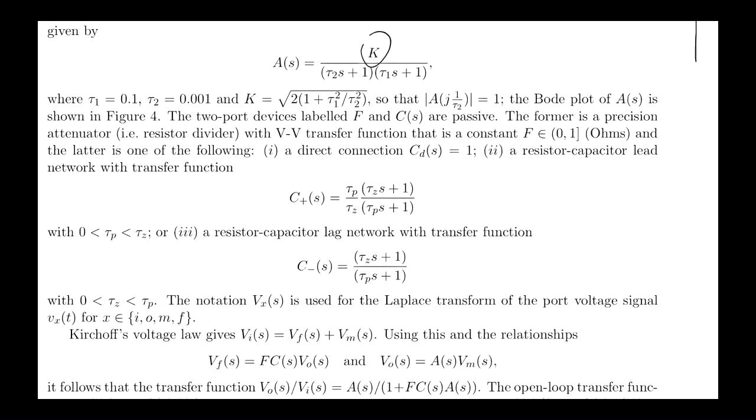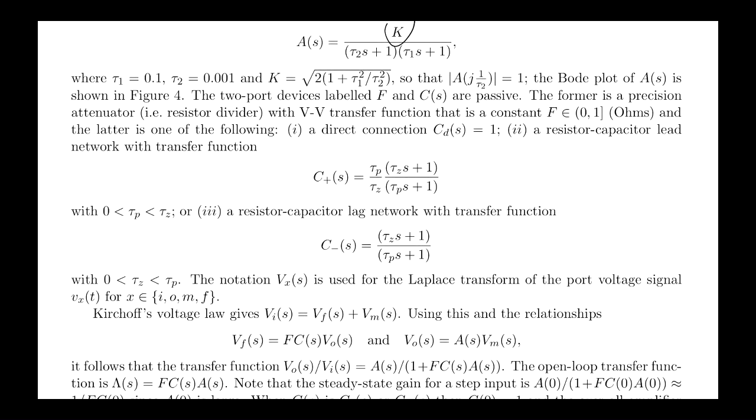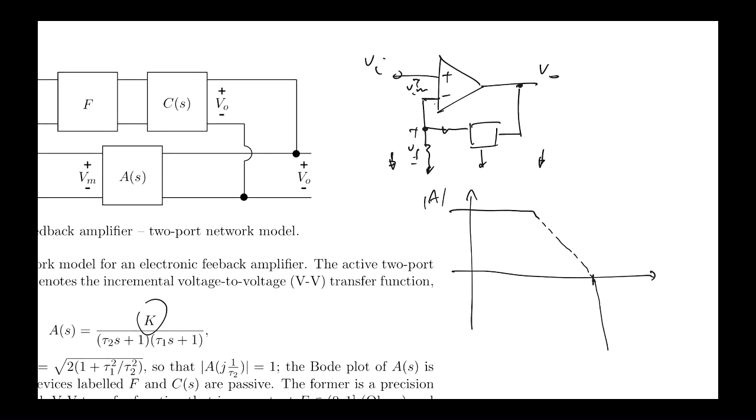All right. So this question is really saying, let's consider what happens when there's nothing in this box. And so all you have is feedback of a fraction of the output voltage to the negative terminal. That fraction is determined by the ratio, this is a resistor divider network. So you always get some fraction of V0 being fed back like that.